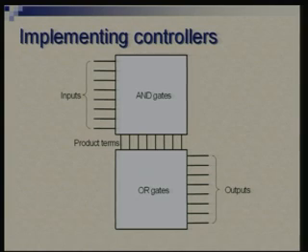So, the inputs go to the AND plane, the output of the AND plane is a set of signals representing the products, and the OR plane sums those products to form the sum of products and gives the final output. So this is the overall outline, and what goes inside the plane is a direct correspondence of what you have put down in the truth table.